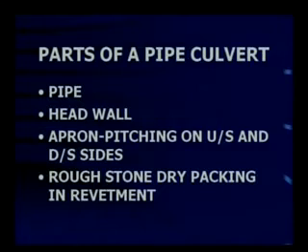The next thing is a rough stone dry packing in revetment. I shall show you in the next slide what a revetment is. In order to support the head wall, we can either construct wing walls on both sides or we can provide slopes. In case slopes are provided, these slopes are covered with a blanket of stones, and such a blanket is called a revetment. Let me show you a model now.